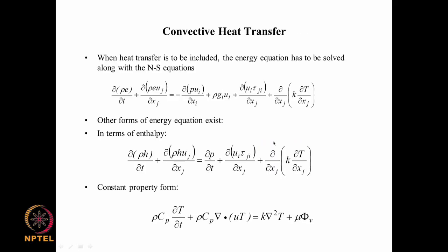So when we look at convective heat transfer, when heat transfer is to be included, the energy equation has to be solved along with the Navier-Stokes equations, because it is only from the energy equation we get temperature, and only when we have temperature we can talk about heat transfer. But we also see that the temperature equation has a velocity component that is coming from here, and there is also viscous dissipation.